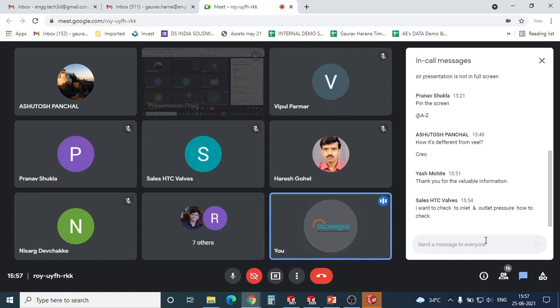If you talk about the meshing, we have the option. You can perform it with tetrahedral mesh, right? Even we have included hex elements; different types of elements are available inside the software. Even if you want to perform it with beam elements, 1D elements, or 2D elements, shell elements, that can be done. And if I talk about 3D elements, then the tet element is available. Also there is the hex element. So all these elements are available.